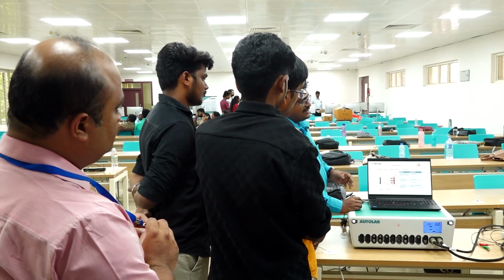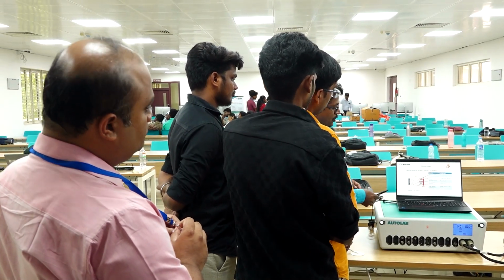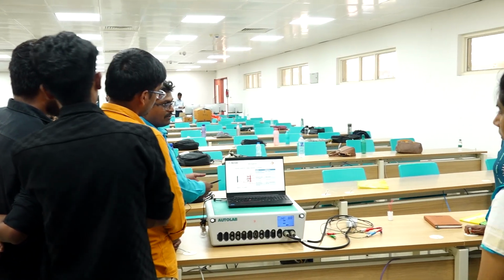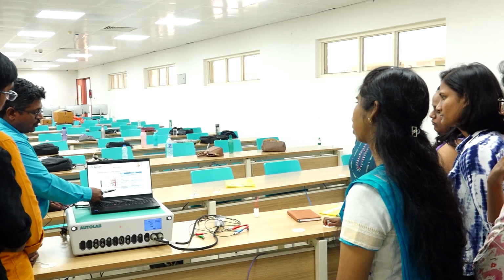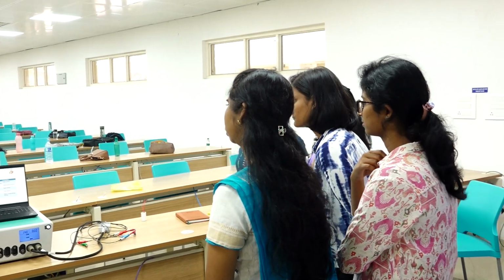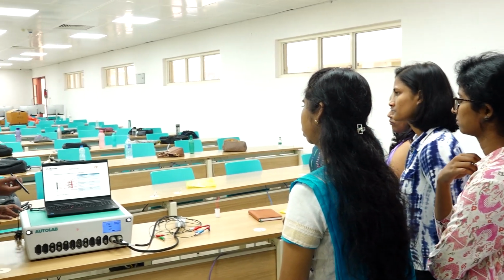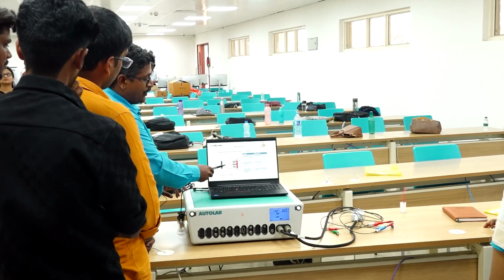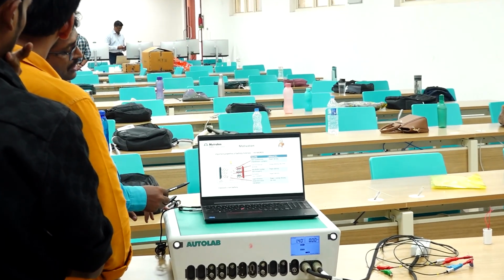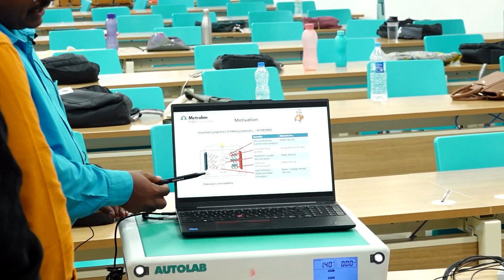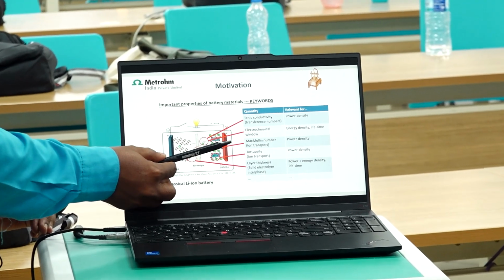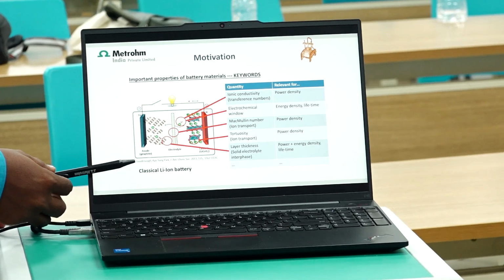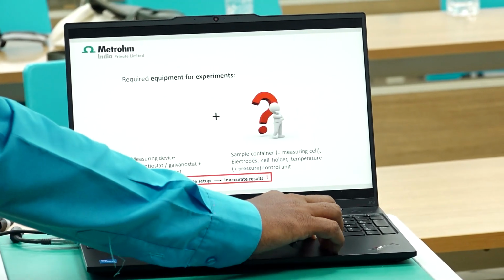So this is how the lithium ion battery will look. In the anode, you will have graphite with lithium modifications or some metal modifications, and the cathode will have a lithium metal oxide, like lithium cobalt nickel oxide, or a different composition. In between you have a separator and an electrolyte. So during charging, what happens? From the anode, the lithium will move to your cathode, and during discharge the same lithium comes back. So this is how the internal process behaves.